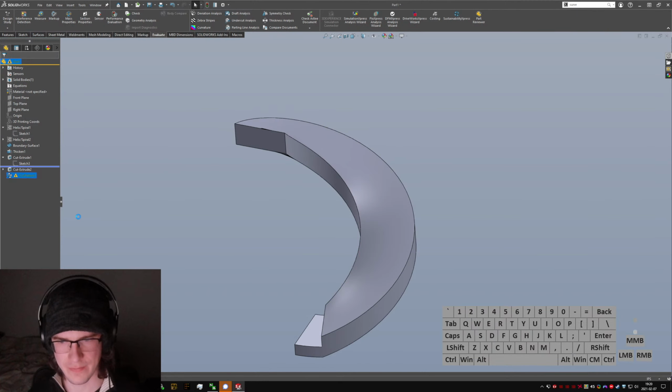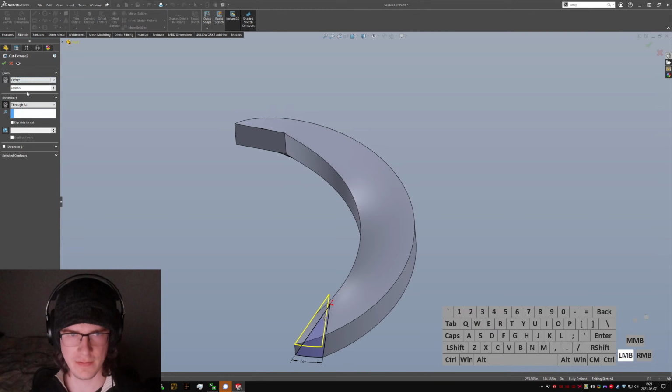We're gonna try, instead of doing the cut pattern from the bottom up... Actually, hang on. There is one other way I can try to make this particular method work. If we do an offset, come up 16, so that we're on top of it, and then we cut back down by 10, or by 8, or whatever our tread height is. Intended cut does not intersect the model. What do you mean? Oh, there we go. Now it intersects the model. And now it works. But it's still broken.